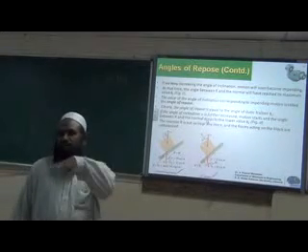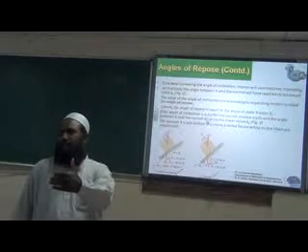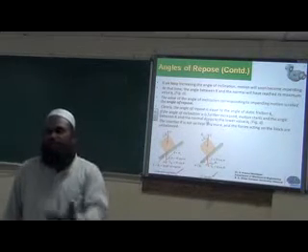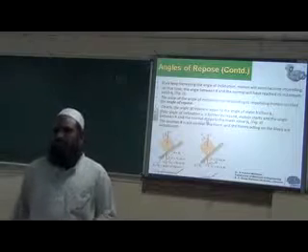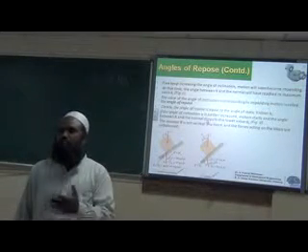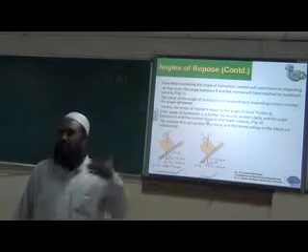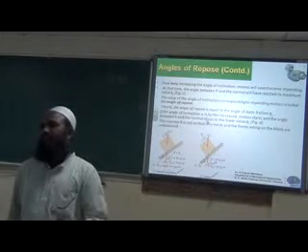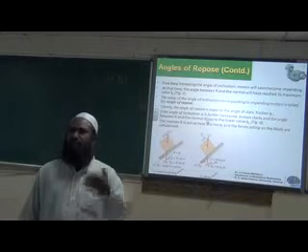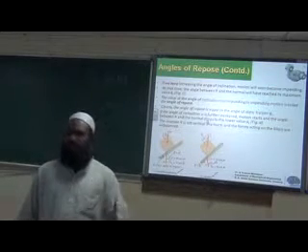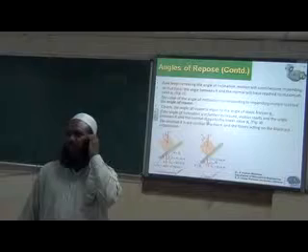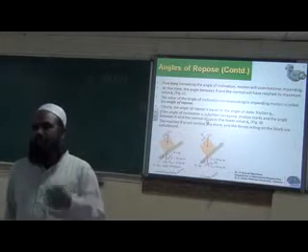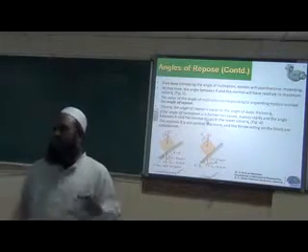Okay. So that friction which opposes the motion till the body starts moving, we call it as static friction. And as the body starts moving, that means the friction becomes less than the applied force. The body will be moving, but still there is some friction. Okay, so the friction offered as the body is moving, that friction is called kinetic friction. Generally, kinetic friction will be less than static friction.